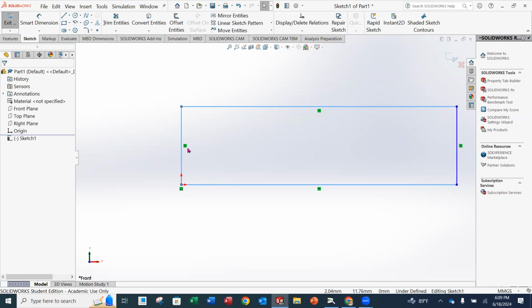As we created that, SolidWorks assumed, oh, you want these lines to be horizontal and vertical. So when you are creating things, you're going to see these populate in. But more often than not, when you put all your dimensions on and you're wondering why you're not fully defined, check for this kind of stuff. If you don't have that horizontal line in, you can add it in.